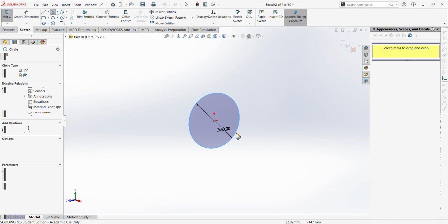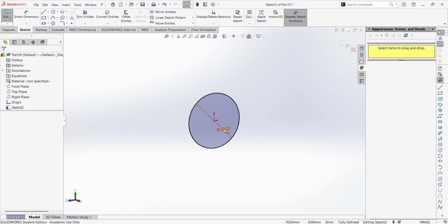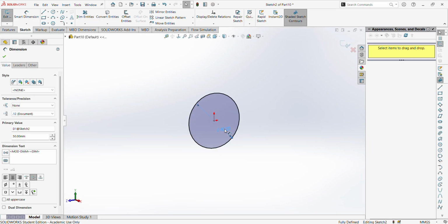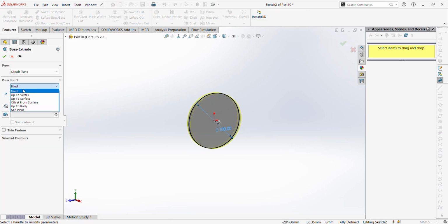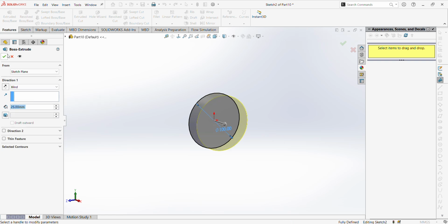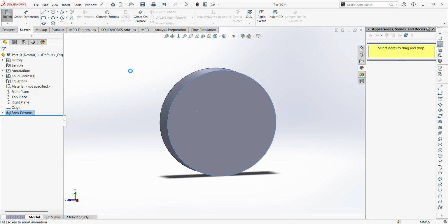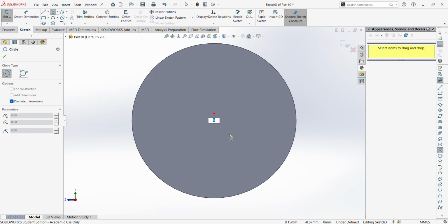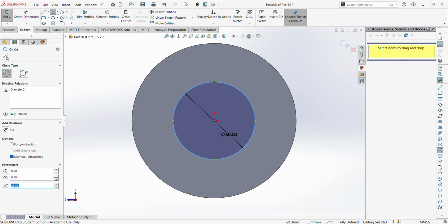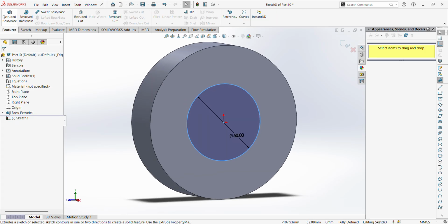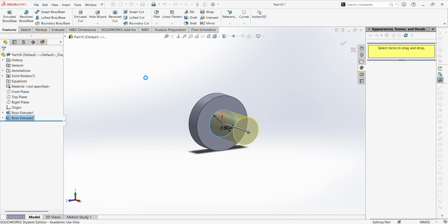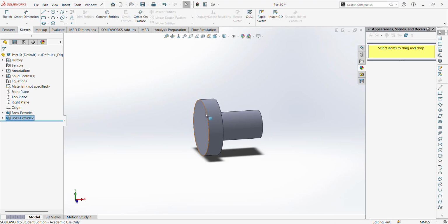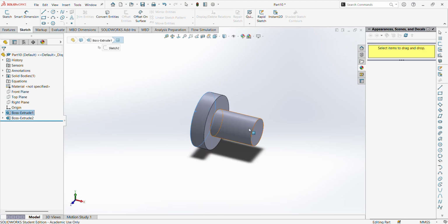Yeah. So see, things get a little bit weirder when you start working in different measurements like that, or different styles. So let's do that, and I will extrude it. Yeah, forward, not mid plane, 25. Cool. And then we could always sketch on this front plane, draw another circle, and I think that one would have been 50 because it's 25 radius. And then we could extrude this off 75. Yep. And then we could sketch the back and make our box and do all that. And it comes out the same.